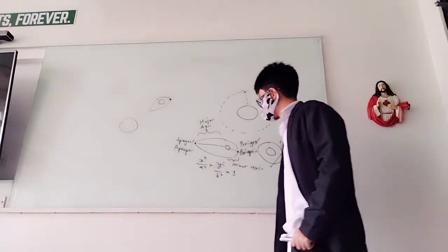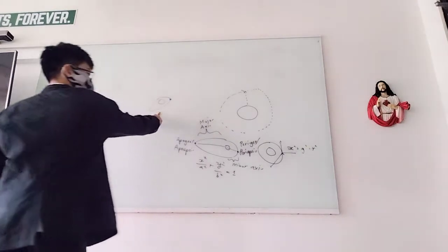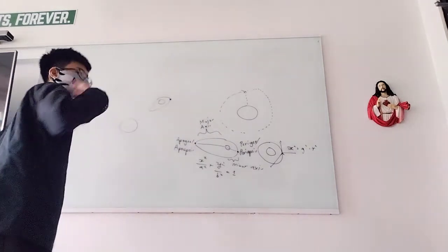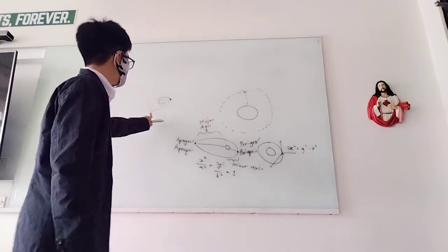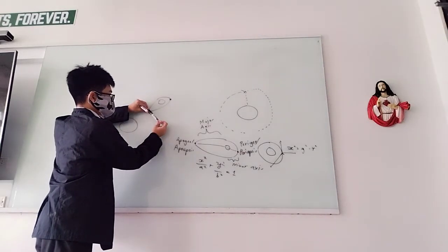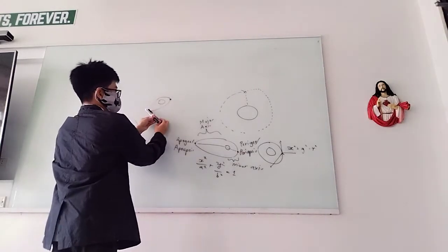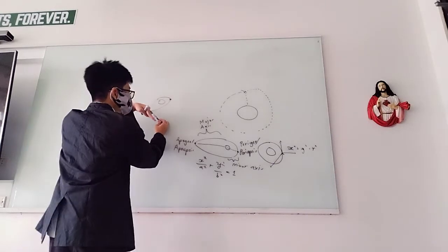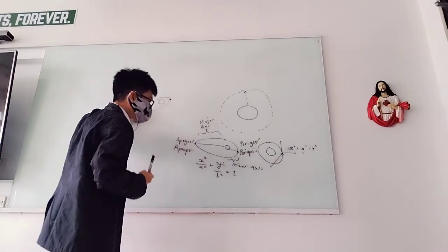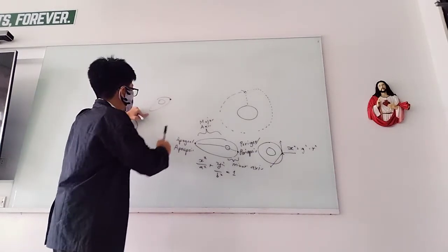To stabilize your orbit, say you have an elliptical orbit and you want to make it a circular orbit. Say your velocity vector is pointing this way. You want to burn in the direction of your vector directly at your apogee so that the perigee would grow.